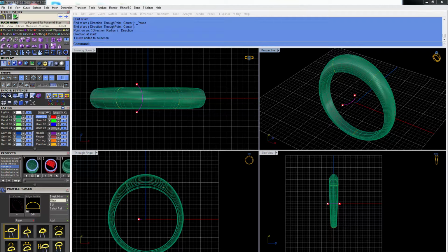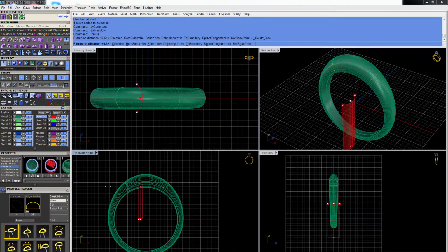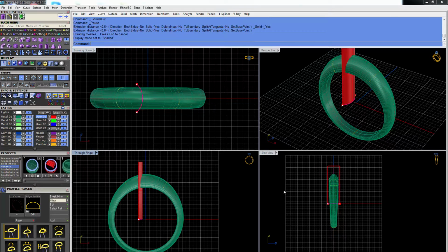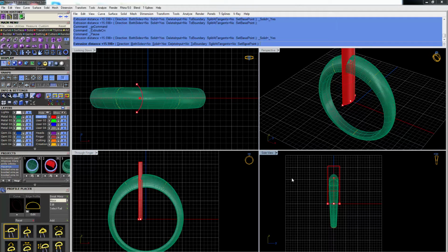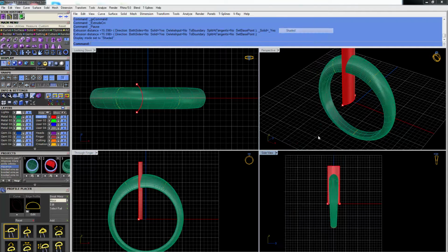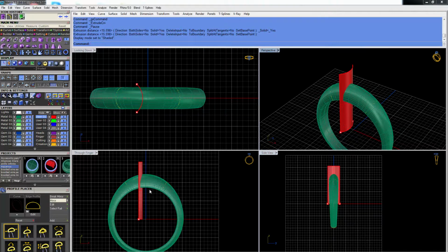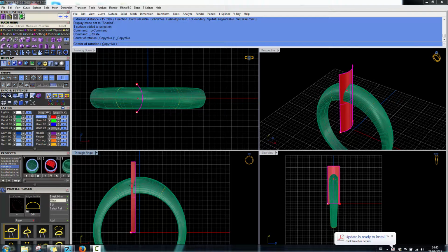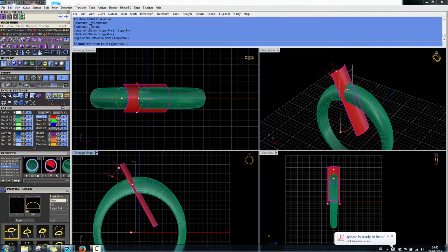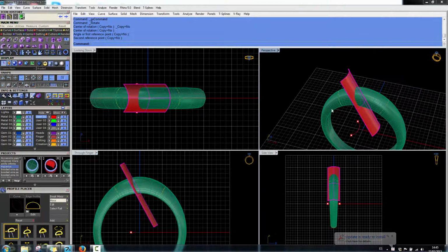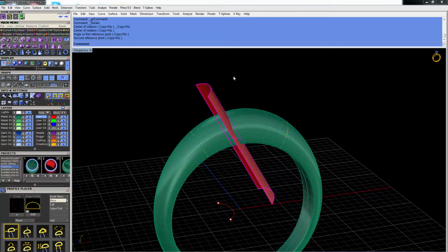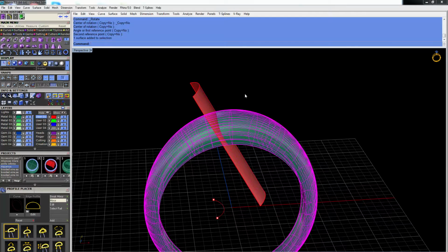Okay, I'm doing this because now I want to turn that curve into a surface. So I'm gonna go to extrude and I'm gonna make a surface. I'm gonna go and shade it here as well and here as well. Shade it. Okay, and now I'm gonna use this surface and I'm gonna rotate it. I'm gonna move it a little bit. Yeah, something like that should be okay. Okay, and then this is a surface now and this is solid.